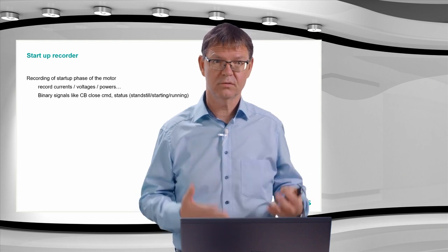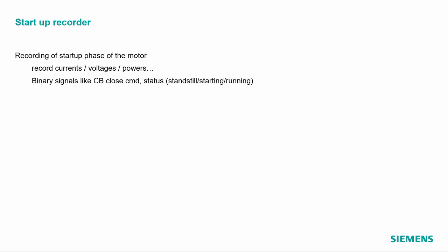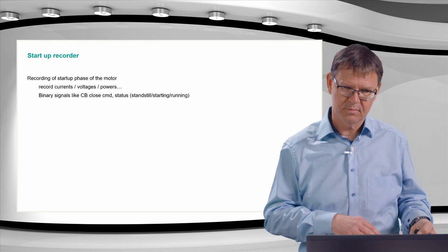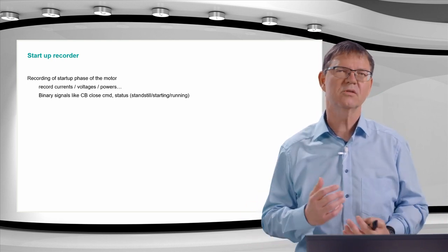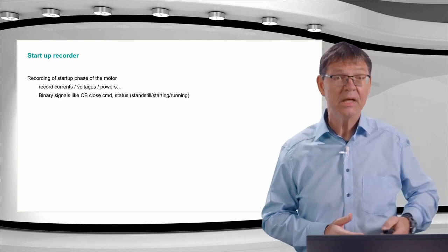This is to record, of course, the startup phase of the motor. We can record currents, voltages, powers. Binary signals like the breaker close command, status of the motor, standstill, starting, running. This is mainly what we have as a default setting for that.